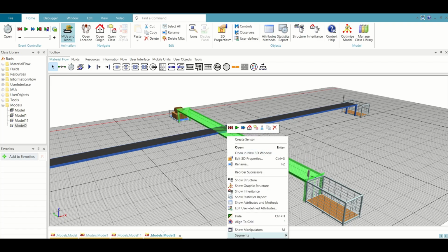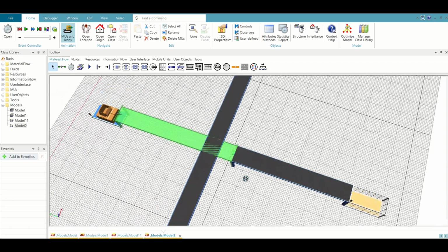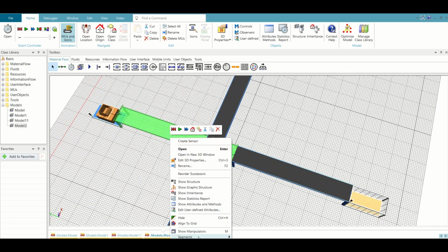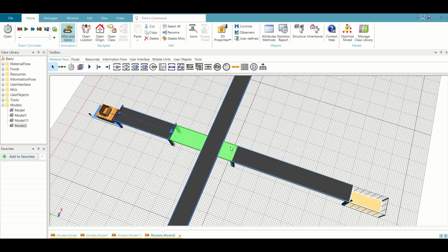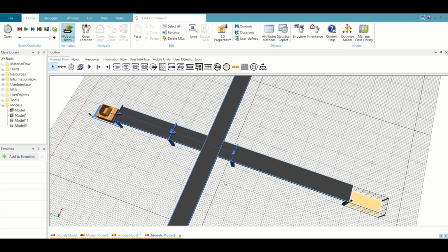Okay, so if I click on split up, right, and then I again go here and click on split up, I have two segments out here now, and let me have manipulators visible for this, right, I click on this anchor, and Control Shift upwards.